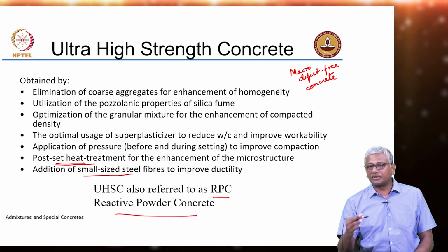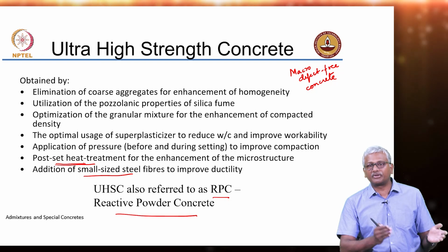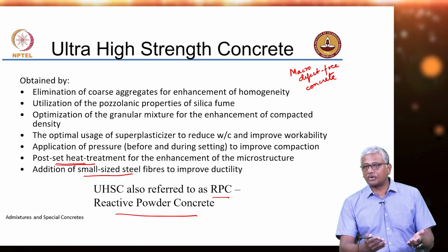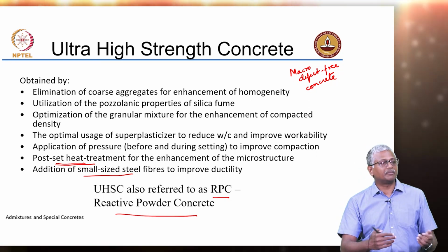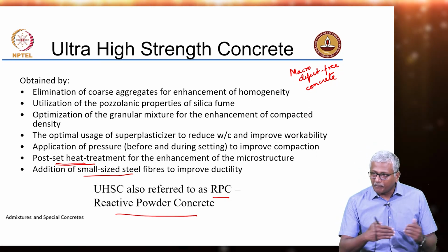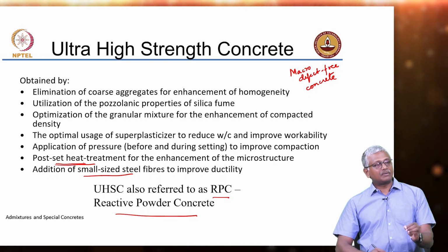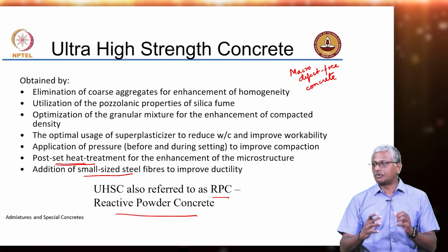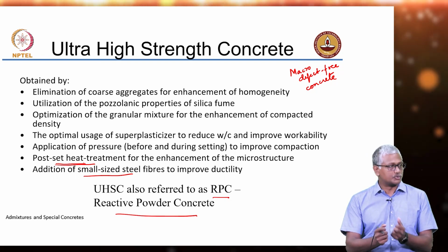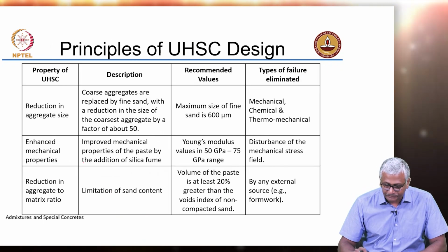But you have to think about it in a different way. Ideally, strength is related to porosity of the concrete. Minimization of porosity is maximization of strength. So how do you minimize porosity? By ensuring that you have a compact packing of all the materials that are available, but at the same time you need some minimal hydration level to ensure that the skeletal framework actually is formed. Otherwise the particles will be loose. Some minimum level of hydration is absolutely important.